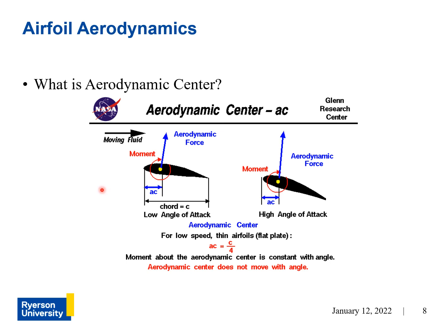Now recall that in order to calculate moments, you need an arbitrary reference point, and the aerodynamic center of an airfoil is an arbitrary point about which the pitching moment remains constant as you change the angle of attack.